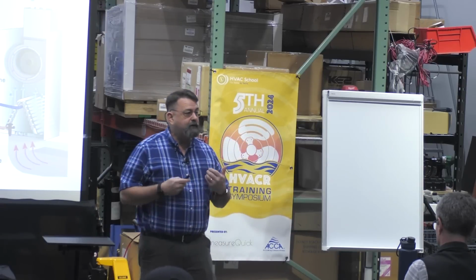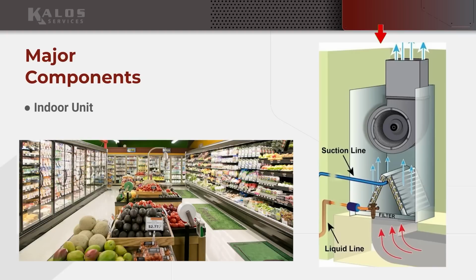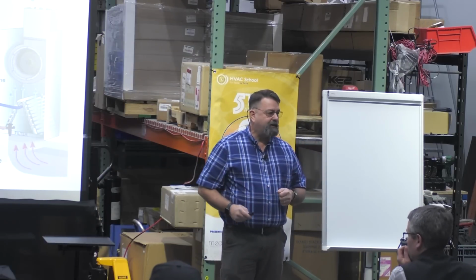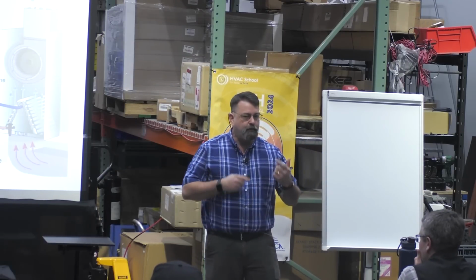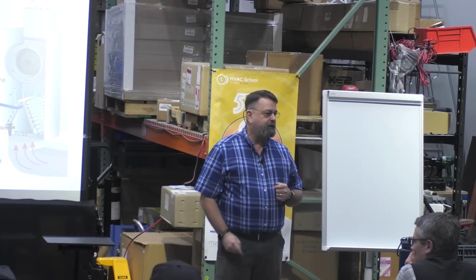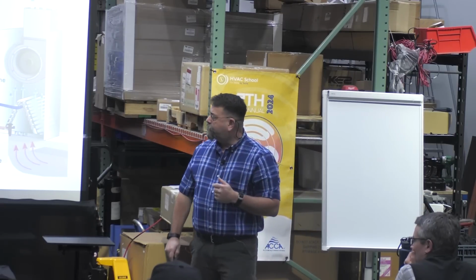We're going to have the same major components. In your air handler on a residential system, we've got return air, we got supply air, we got a blower that's making that happen. We've got an evaporator coil, right, where our refrigerant can change state because of our metering device. We got liquid refrigerant coming in, we got our suction going back to our compressor. I've got all of that going on inside these cases as well, right? So that part just looks different. And we'll break it down and look inside one of these cases as we get through this a little bit.